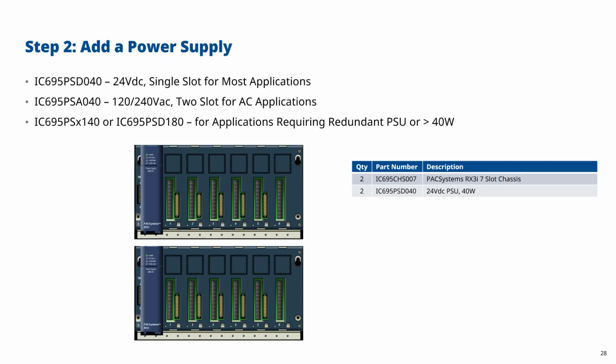But if people are really into redundancy, you could add a PSD140 into each chassis and you'd have 2 of those, which would have total quantity 4. But I would say for most applications, there's a law of diminishing returns, and adding redundancy on top of redundancy doesn't really help you much. And actually it can make the system less reliable, because the more components you add, of course, the more likelihood there is of a single point failure.